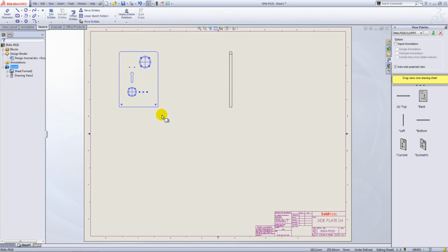This can be good for sharing your drawings. If you send these drawings out to someone and your views are saved as blocks, you won't need the reference files. It could also be good for archiving versions of your files, and it also reduces the overhead of the drawing as well. Okay, back to Ed.